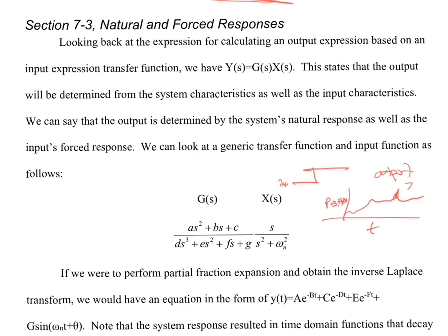Well, the problem is this system was designed in the 70s and there was no data. I was involved with developing a first order model of this massive moisture separator reheater system so that I could come up with a tuning constant so that it would heat up slowly and not overheat the system. Because if it overheated, it went into alarm and then it would trip into manual mode, and then you had to have the operators do it manually.